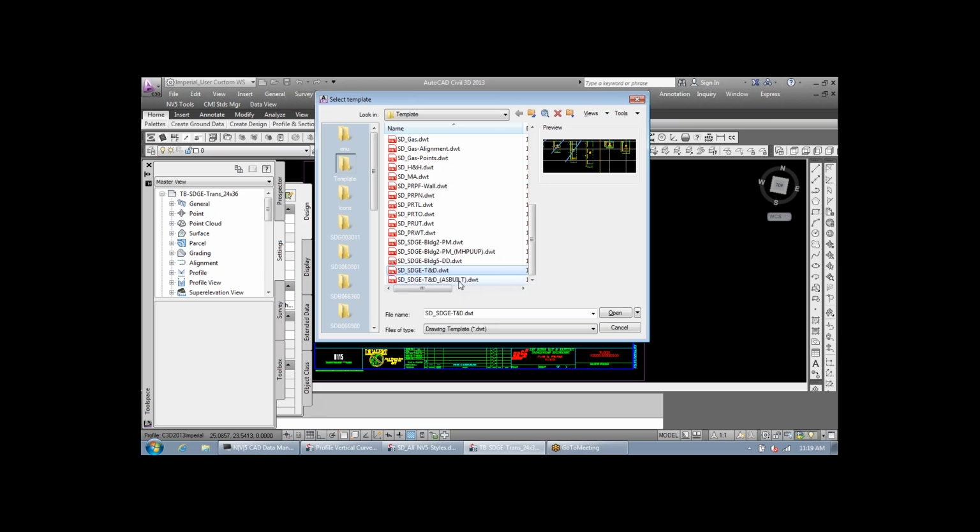Creating an EXTO. This has been an issue here as of late. How do you create an EXTO and what goes into it? Your EXTO should basically be a background base drawing of existing topography and planimetrics. Anything that basically the aerialist picks up. What you're going to do is create a copy of the file that we received from the aerialist, throw it under the master folder. Whether or not you want to start using that file, probably okay. However, you're going to make a copy of that file and rename it C3 as well, EXTO C3.